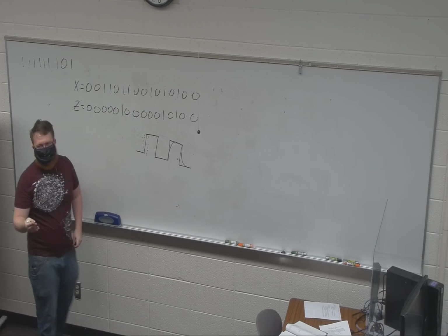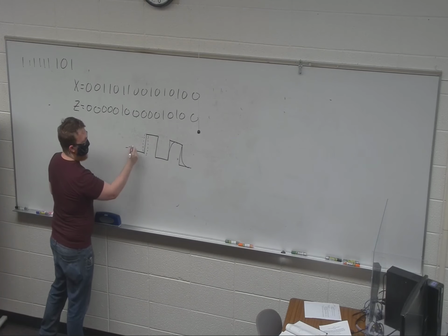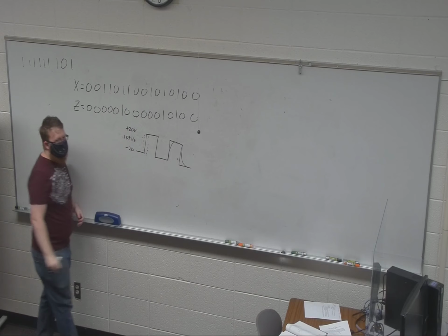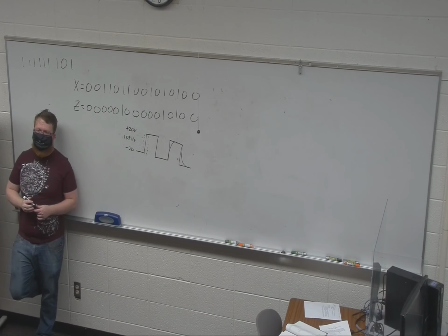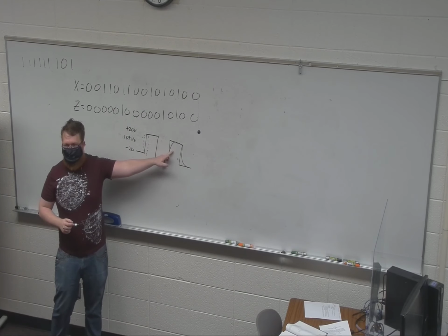But to do this in a particle accelerator, my clocks were minus 20 volts to positive 20 volts. And I was doing this at 10 kilohertz, and to drive all that capacitance took between 1 and 3 amps of current. And my clocks really started to look like that.